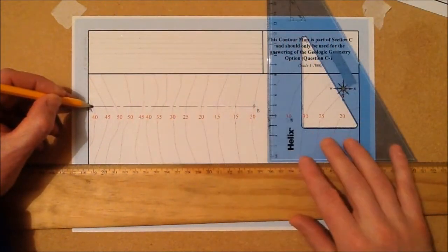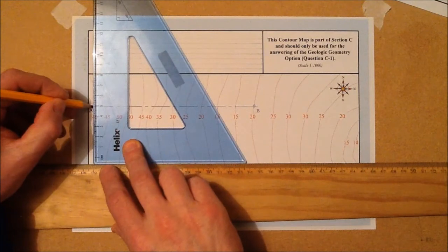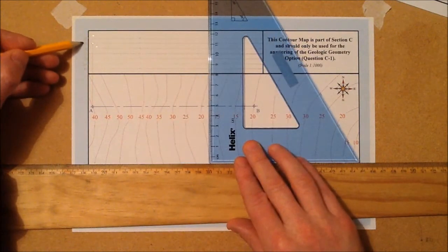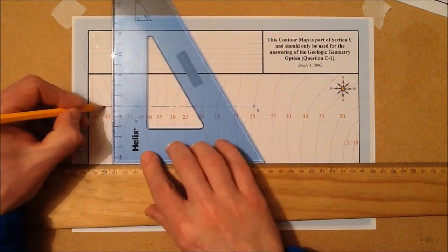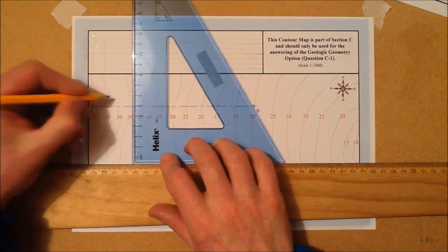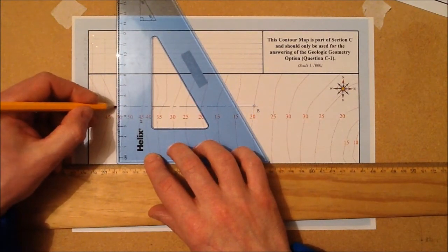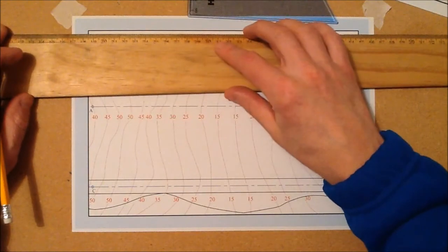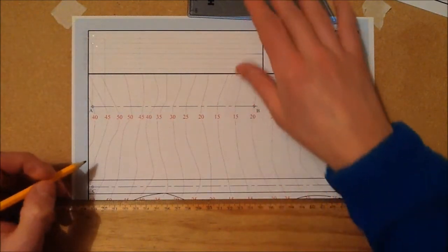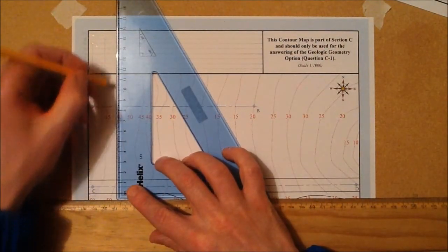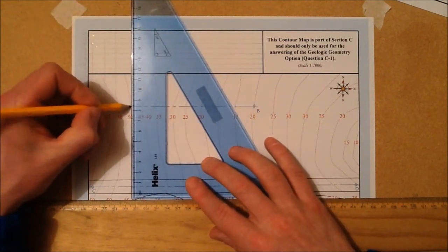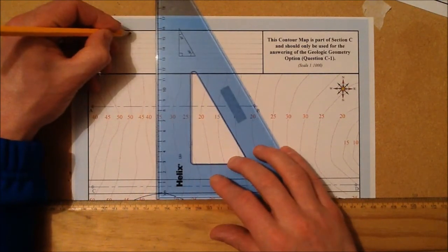If you see, I start here with the first point on A, which is on the contour at 40 meters high. I'm going to bring that up and mark it on the corresponding height here, which is 40. Likewise with the next one, I bring that up to the point where it hits the contour at an altitude of 45 meters. I'm going to continue on through those and bring them all up to the different heights. I've actually forgotten one height here at 50 meters, so I'm going to mark that in, and that's at 50 meters as you see. I'll carry that up to the 50 meter contour and plot that point. Again, I'm just going to carry on through with all of those until all my points are plotted.